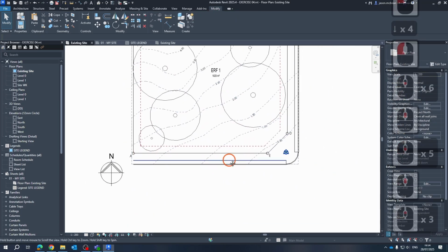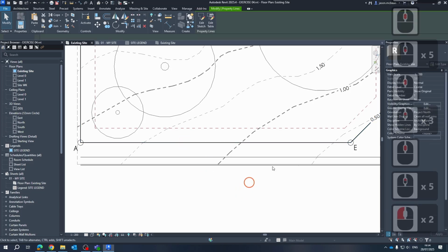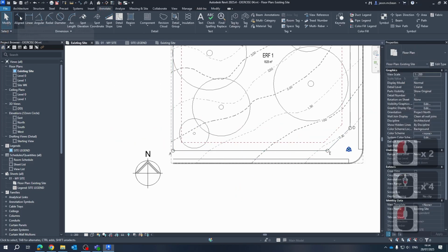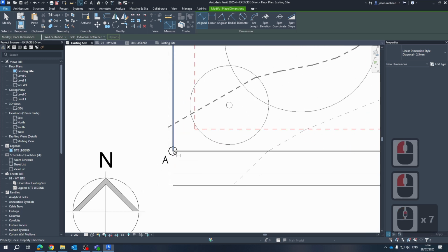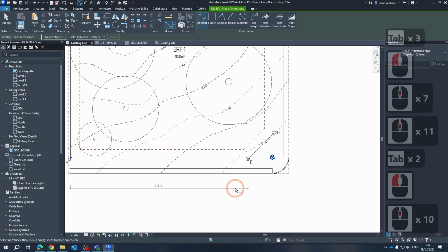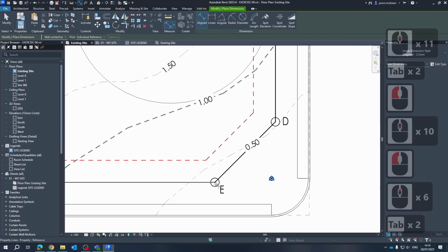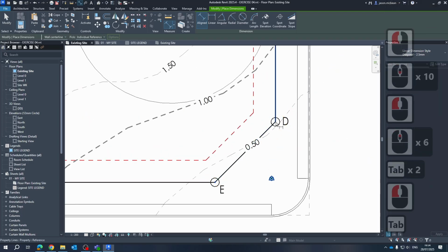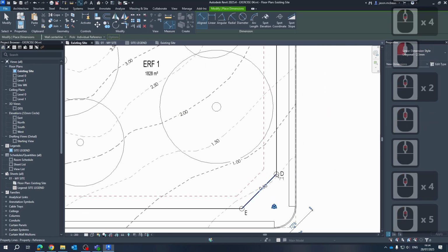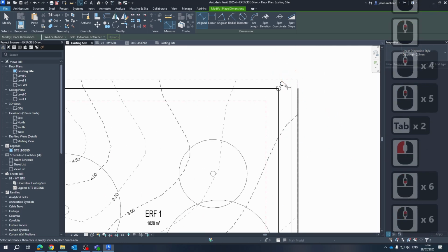The next thing we're going to do is add our boundary dimensions. So we're going to go to annotate, aligned. Remember, if they're not exactly aligned, you're going to press tab until it highlights a point. I just use quick dimensions so that if I am making these notes, I don't make a mistake. There is a tool to do this, but for now, as part of this exercise,